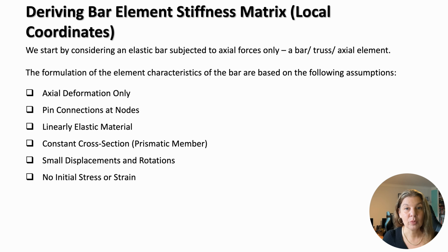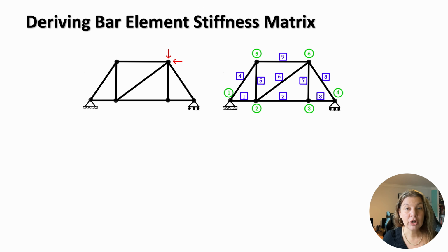This means that in this case we are talking about a two-force member with only two equal and opposite forces acting at the ends of the element, along the axis of the element. The basis for the stiffness method relies on the load displacement relationship at the nodes of each element. As we discussed in previous lectures, trusses are structural systems which consist exclusively of straight members connected at joints located at the ends of each member. Trusses are only loaded at the joints. Since all the joints are pinned, members of a truss only experience axial forces along the member. This is just like the element we're describing.